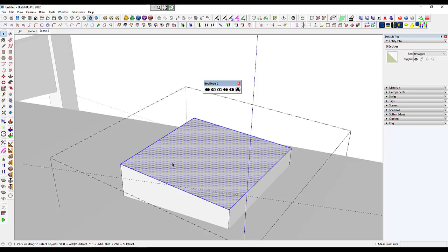Again, I'm going to select those edges. It's faster to select that by double clicking on the face and then holding shift and deselecting that than it is to go around and select each of the edges. And since they'll stay selected while I draw in these edges for the fold lines, I'm leveraging that.